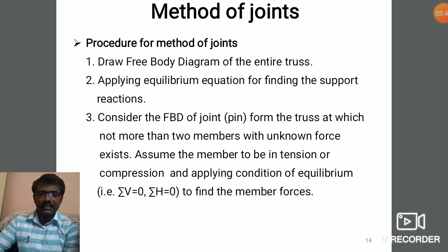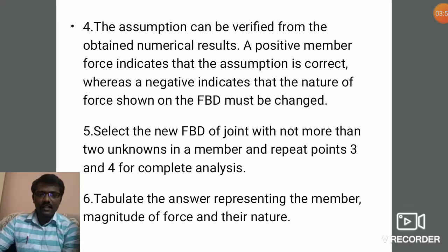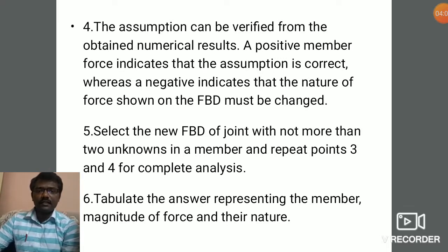Then we apply the static equilibrium equations, that is summation of V equal to 0 and summation of H equal to 0, for finding the member forces. If the answer is positive, our assumption is right. If the answer is negative, our assumption is wrong, and we change the nature of the force.